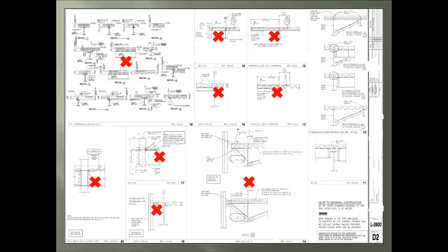Ninth X covers the perimeter concrete panel attachments. 10th X covers attachments located at seismic beams and drag strut connections. The 11th X covers tube steel spacer for slab support. The arrow takes us to notes once again for the general contractor and approver.